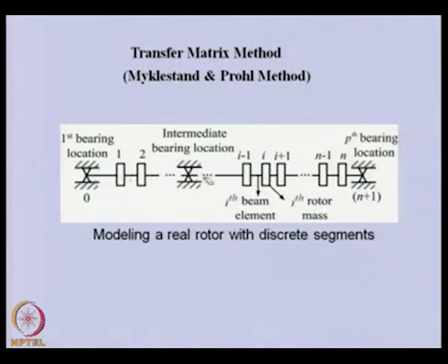So, now for developing the point matrix or field matrix, we need to take out some representative beam segment or rotor segment, and then from the free body diagram of that we will try to derive the field matrix and point matrix for these segments. For support, we will have a separate treatment, because here support will give some unknown reactions. So, to tackle that we will see through some example in subsequent lecture how the support can be taken care of if there are some intermediate supports.